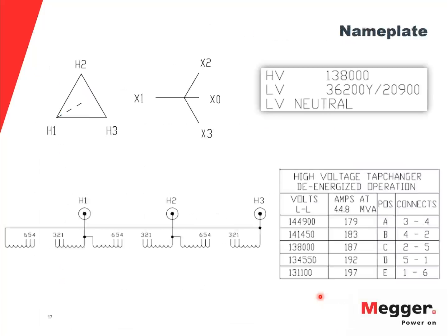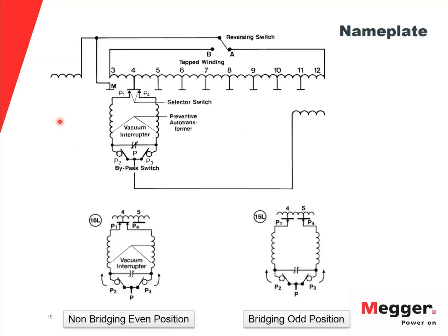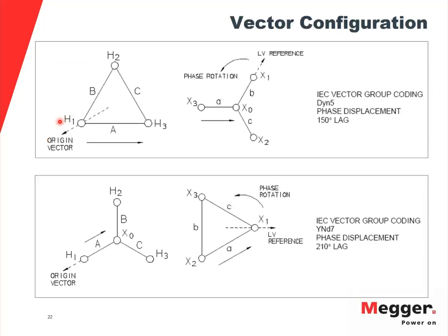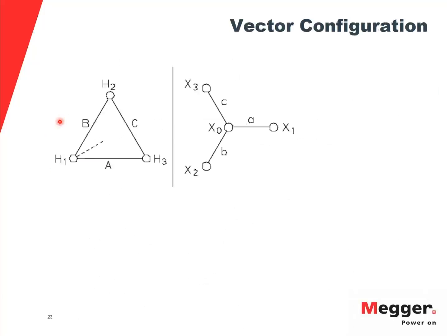Sure. Good morning, everyone. Once we go back to that, we'll start again on slide 17, then I'll have you advance through them. But basically, this dotted line here is your phase reference. So this is on the high side here, and it's your phase reference. And if we go to the next slide, yeah, thank you. If we can go starting right here, I'll go back one or two. So if you go here, once again, instead of a dotted line, now we're drawing this arrow through once again for the phase reference on the primary side.